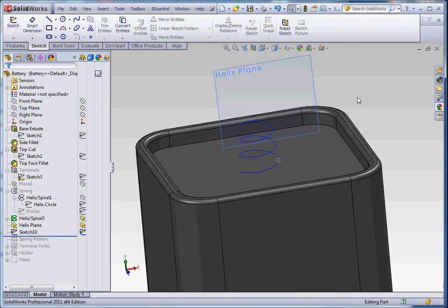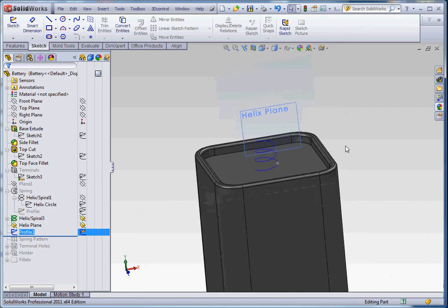So remember the sweep. Sweep needs geometry. Actually, it needs 2 independent sketches. One's going to be the path, one's going to be the profile. And from there, we're going to go ahead and choose our elements that we're going to be used for our sweep. So I'm going to call that profile 2, because we're profile 1, because I already have one. Okay, there we go.